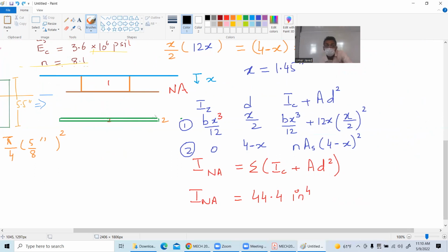So for example, these are two cross sections. This is concrete, and you remove the rebar. This is not rebar, by the way. I removed the two bars and filled in concrete, so the whole green portion is just concrete. Now, if you have this as section 1 and this as section 2, and I have to find the moment of inertia of this section about what? About the neutral axis. I love the neutral axis. That's why I found the centroidal line, because my centroidal line was the neutral axis line.